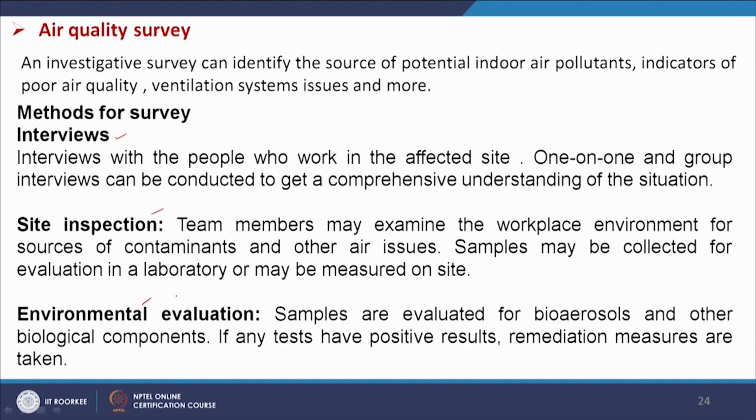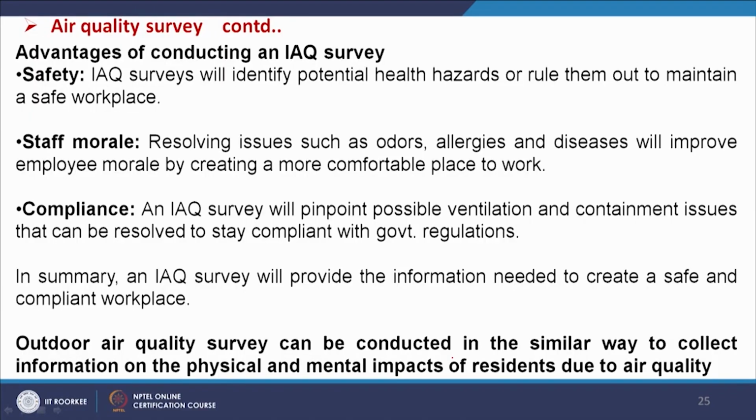Samples may be collected for evaluation in a laboratory or measured on site. In the environmental evaluation, samples are evaluated for bioaerosols and other biological components. If any tests have positive results, remediation measures are taken. Due to this indoor air quality survey, we can get some advantages. That is safety. The IAQ surveys will identify potential health hazards or rule them out to maintain a safe workplace.